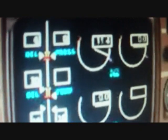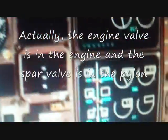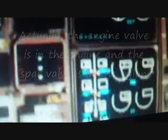Now when you switch to ground, the bleed air valve opens, lets air into the starter turbine, spins the N2 high pressure compressor, and this is the indication we see, 18%, 19%. Now in this aircraft, with these kind of engines, the maximum N2 is 23%. Then you open the engine valve and spar valve. The engine valve is a fuel valve that's actually from the pylon to the engine, and then the spar valve is from the fuselage to the wing.